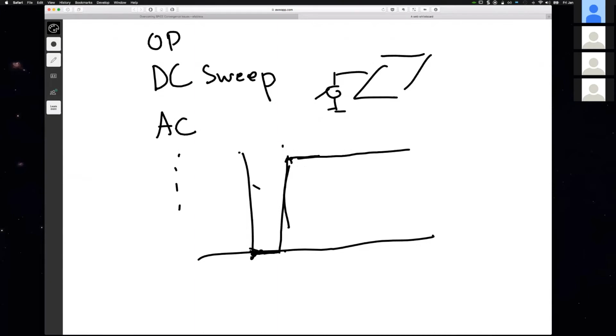Now, some circuits, if they intentionally choose, would wait until the supply and the system actually rise to a certain state, and they intentionally want to make it a power down state, standby state, where some of the nodes are forced to 0, so you can have a completely controlled scenario rather than letting it be alive with the supply. And then you enable it, and you have a signal that would trigger other activities in the circuit. So that's the real world, and it happens this way.